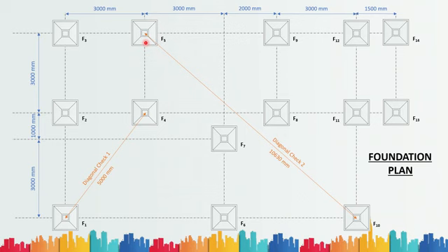Now why this step is very important is because the foundation is the first thing that is constructed on the site, the first thing that is set out on the site. So if this goes wrong, then the entire building will go wrong. So these checks are extremely important to be done at the very first step.